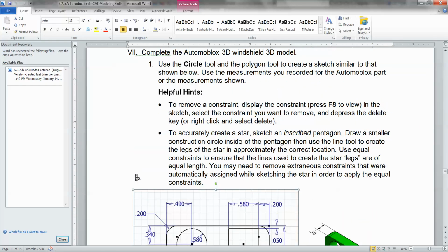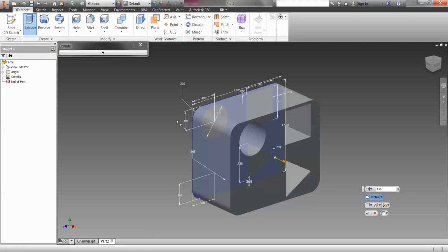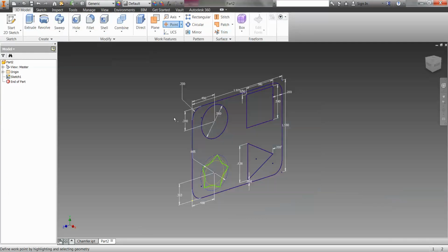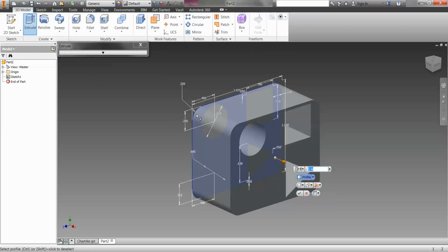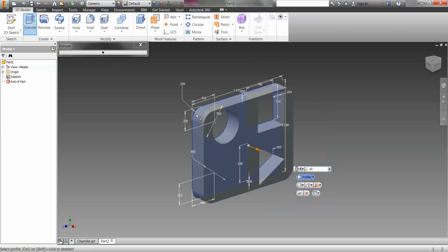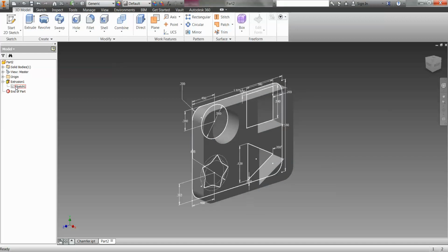This is going to get extruded out here to 0.30. Gives us from this shape over here, so that's fine. We can do that. And set this to try our extrusion again. Come out. This is 0.30. I'm going to do a little something under the extrusion here, open that up, and on sketch